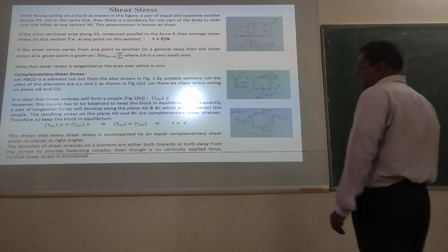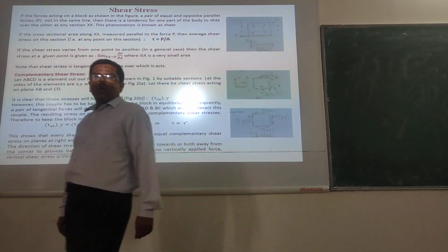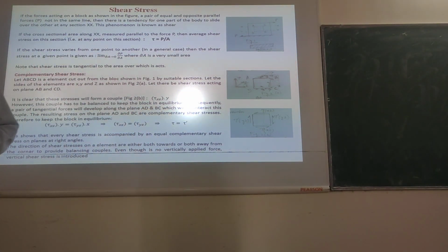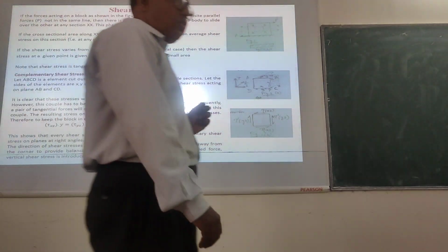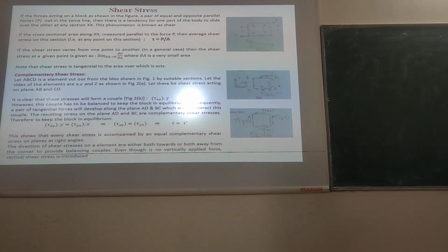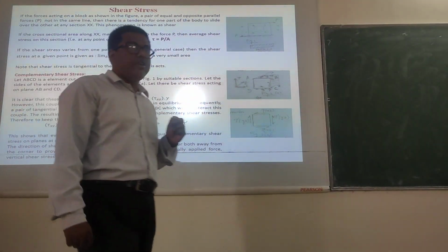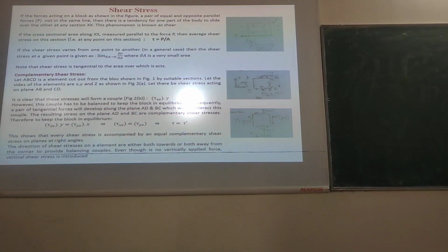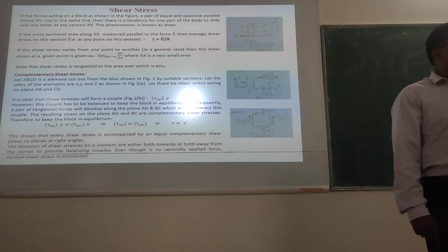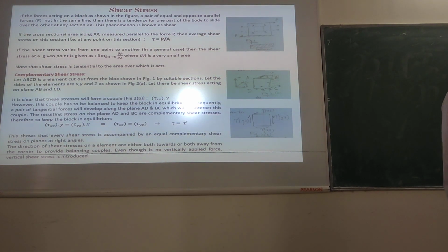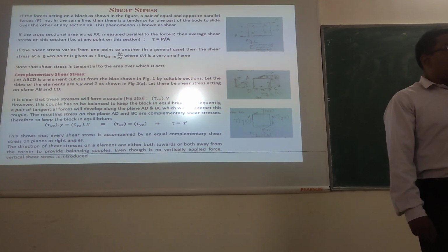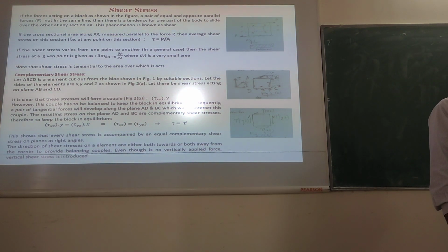Okay, so up to the previous class we have discussed the things related to strain and stress, and particularly we have understood the strain behavior of mild steel and what the different salient points in a mild steel stress strain curve are. We also understood that when there is not a perfect yield point, how to find out the yield point, using the concept of the method of offset and the proof stress concept, right?